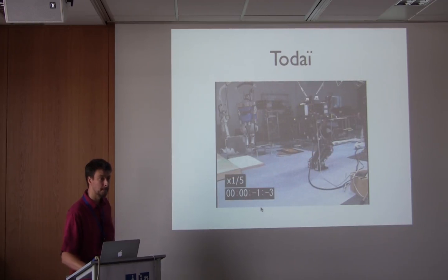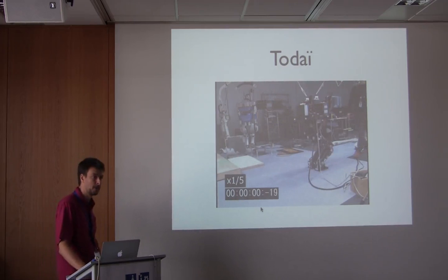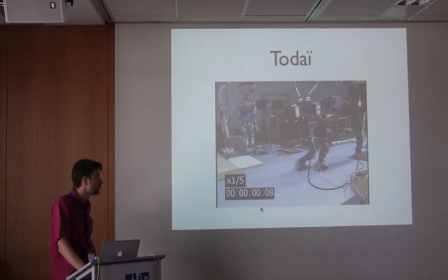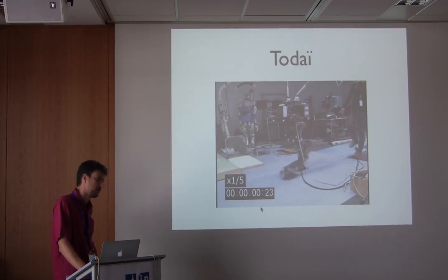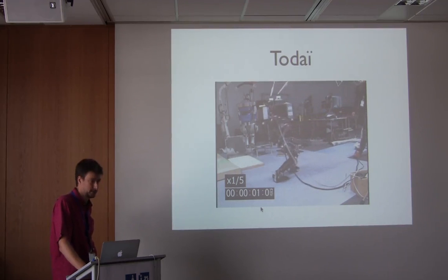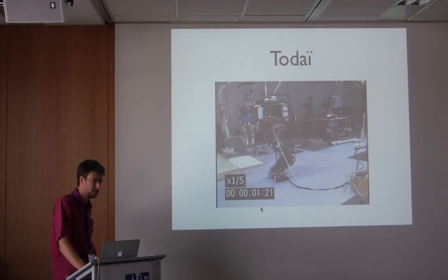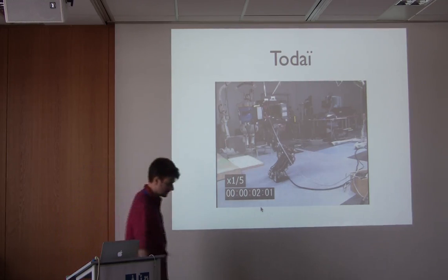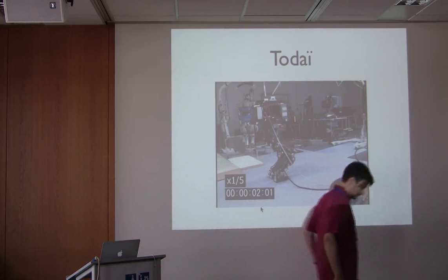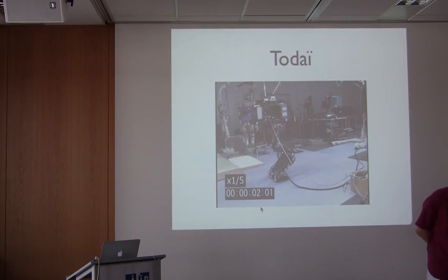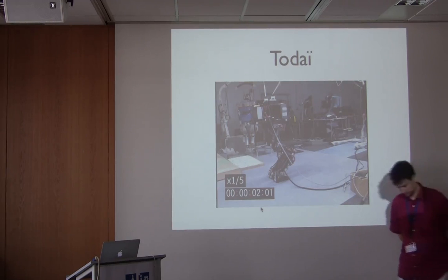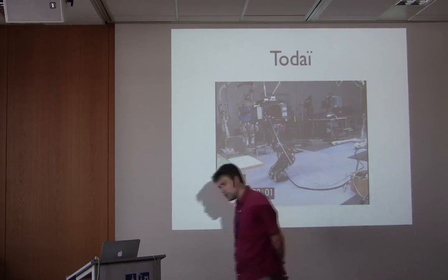But is there a major concern with any kind of motion that we may want to generate on our kind of robot? The fact that we're severely limited in the torque that we can generate in the joints. This particular robot can only do that because they use capacitors to get extra power to the joints. Similarly, the Big Dog from Boston Dynamics and Atlas have these hydraulic generators, so they can actually generate motions, whereas for us, most of those would be just impossible because of the constraints on the torque.